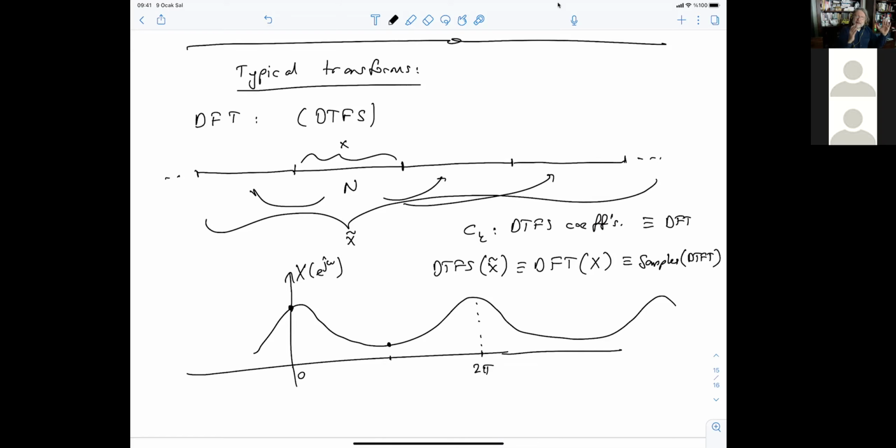So we are sampling between 0 and 2 pi. If you have a 4-point FFT or DFT, sorry, I'm stuck with this term FFT because that's the method to evaluate the discrete Fourier transform. It's the fast method of doing it. It means fast Fourier transform, but fast Fourier transform is the discrete Fourier transform. Just the method is fast. It's the same thing.